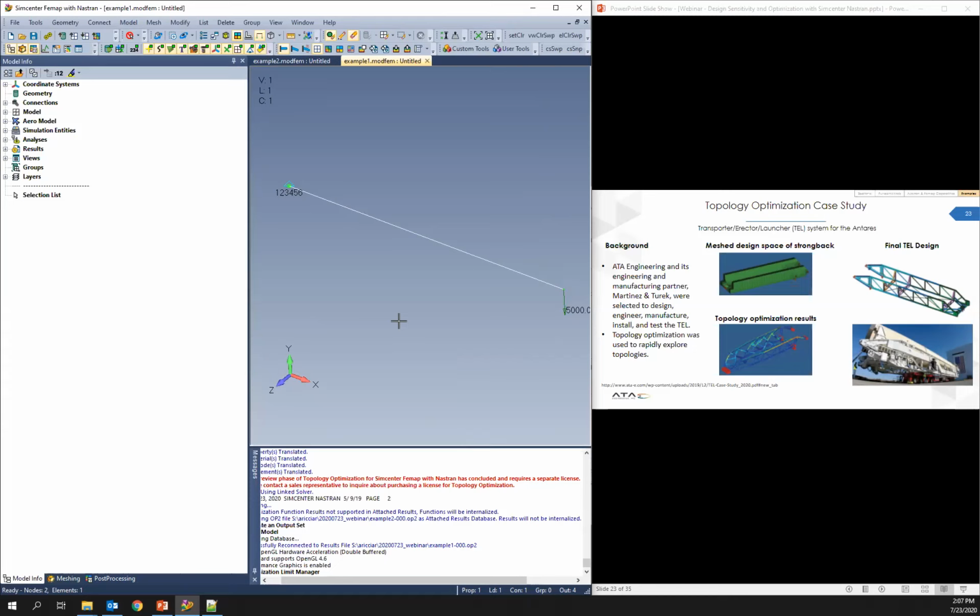But if you're looking to optimize the number of plies, then you may have to implement something differently, either picking and branching your design and fixing the number of plies and then optimizing the different configurations separately, treating it like a trade study where you're comparing two different things. So you can work around that, but the direct support with the internal gradient-based optimizer is going to be limited to the quantities on those laminates that are continuous.